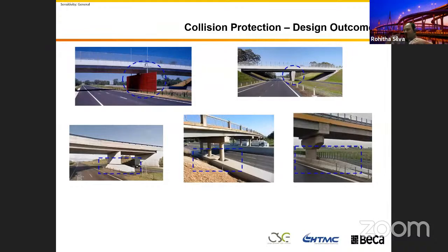2700 kilonewton times 1.2 is close to 3000 kilonewton plus meter overturn on your foundation on the pier. The substructure, the foundation and piles, need to be designed to absorb that load. In our modeling we put this in as a loading, and we checked it if you have not provided, if you have not designed, rigid traffic barriers or deflection walls or protection around the piers. So we had to design that.